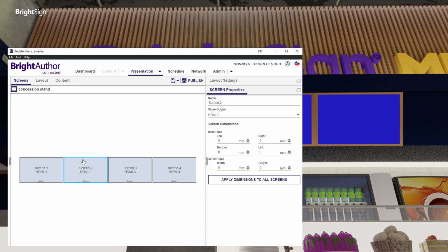So we're going to go ahead and set the bezel compensation here. For this screen, it's going to be 47 here on this side. And then we're going to do 47 on that side and this side. And you can see we're just kind of mirroring this physical space that we've got. And then when we get to the last screen, we just want this inside bezel. The outside we're going to leave alone. So outside bezels not accounted for, inside bezels we are accounting for.